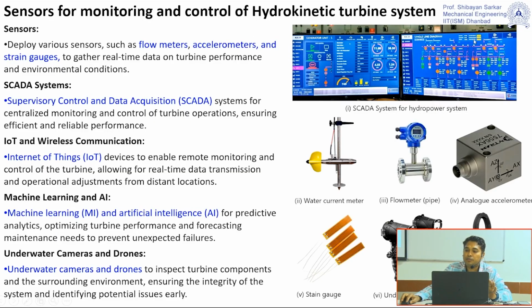This is a typical structure of the SCADA system. Many parameters are fed, and if you set the threshold value, definitely that can give you the warning, and that warning can be in terms of color. It may be red, or it can create noise. That will be based on the capacity of the software of this particular SCADA system. So there are some advanced systems. The data I have told you about is the live system. Live data will be occurring, or maybe data will be recorded in this system. Later on you can access it.